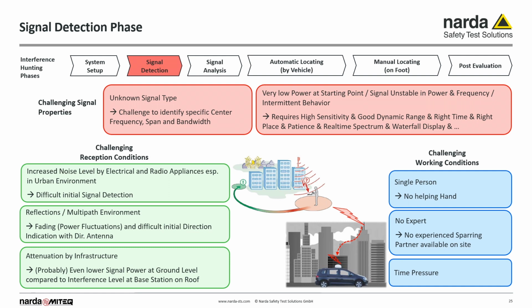SignalShark is not only extremely sensitive, in the telecom bands its typical noise figure ranges around 12 dB without a preamplifier, but it also provides an enhanced dynamic range due to its built-in sub-octave filter bank. This bank of bandpasses leads to impressive dynamic values, which are typically 40 dBm for the IP2 and 14 dBm for the IP3 in the telecom bands.